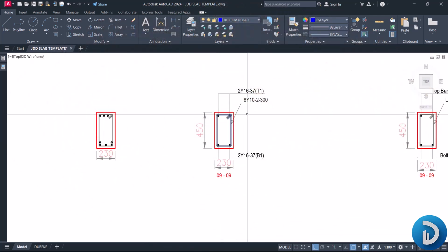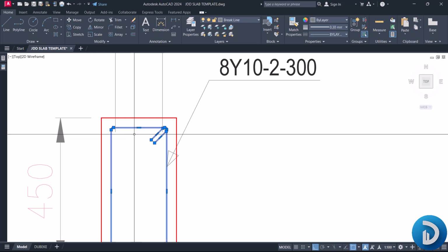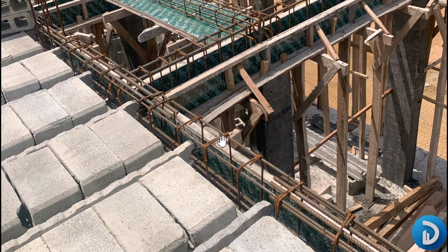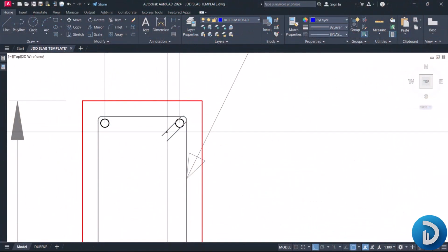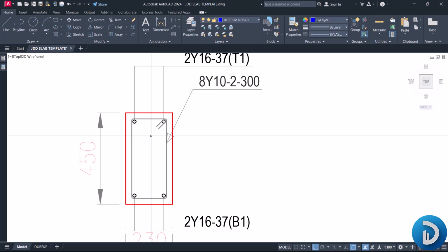Because if we take out this reinforcement at this zone, you will observe that because it's not experiencing maximum moment there, these beams or these links here will be left flapping. Okay, so we have to provide a minimum reinforcement in order to keep these links in shape and also help in shear resistance.